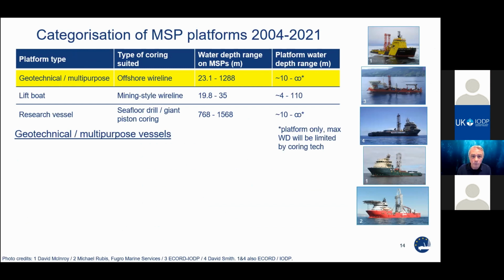So as I explained before, when drilling, the minimum water depth is dependent on the capability of the dynamic positioning system. So you can imagine that a short distance of pipe between the ship and the seafloor has much less tolerance for movement, and so the ship must be more strictly held in position to avoid bending and possibly breaking the pipe.